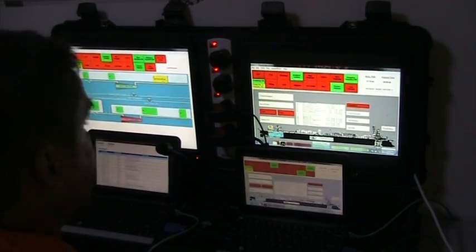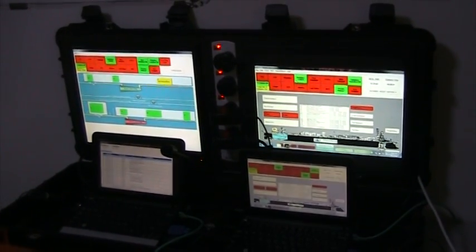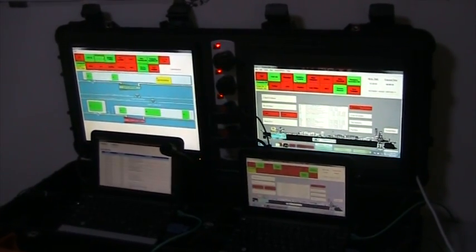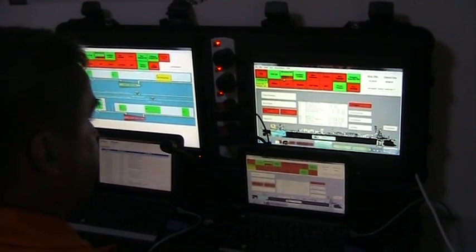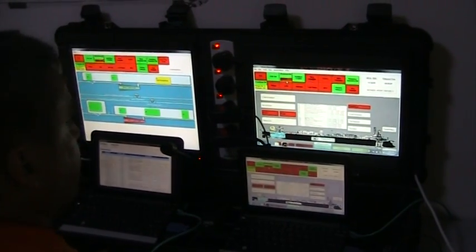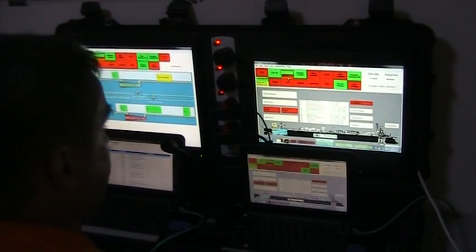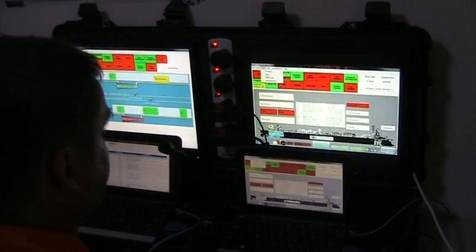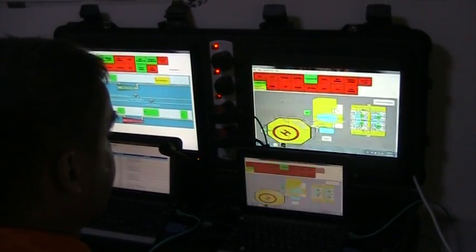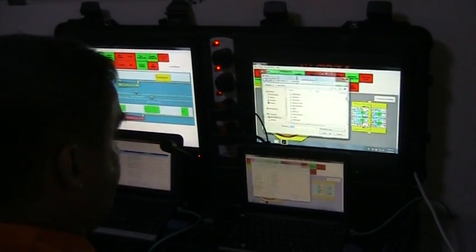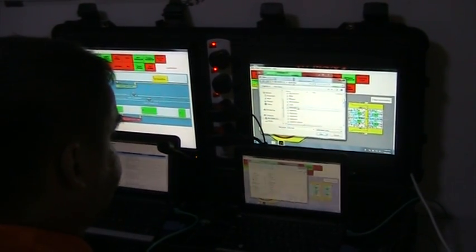Isolations are complete. We can depressurize the plant by going over here and clicking ESD and blow down. You will notice now the countdown here from a preset figure of 1000 psi will blow down to 100 psi in 6 minutes. We can activate the deluge. I can also send through some messages or some sounds. For example, I can send in the sound of an explosion.